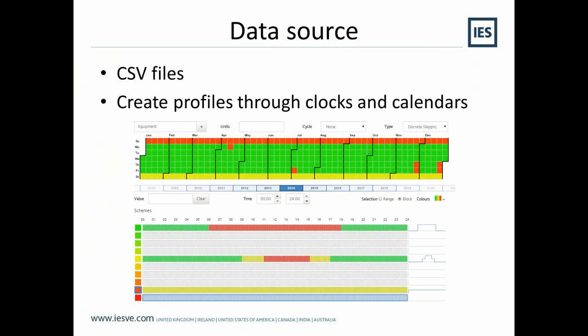So what you can do at the bottom, you get to choose from maybe 10 different daily profiles. You can input your values to control the shape of each day. So that's like a 9 to 5 on off. There's maybe an 8 to 4 stepped profile, and this one's maybe 50% occupied continuous. What you then do is you use the colour swatch for each of the profiles, and you click on what pattern you want that to be.